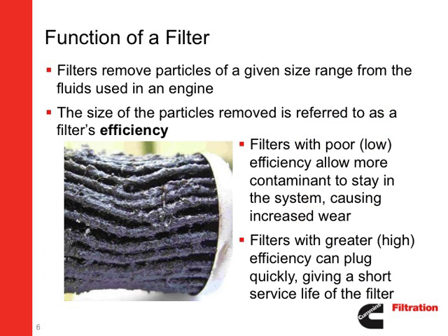It is the purpose of the filter to remove particles of a given size range from the fluids within the engine. Filters are rated by the size of the particles they remove. This rating is the efficiency of the filter. Filters with poor or low efficiency only filter out larger particles, allowing smaller contaminant particles to stay in the system, causing increased engine wear. On the other hand, filters with greater or high efficiency remove much more contaminant, but can plug quickly, giving the filter a short service interval and causing increased maintenance costs.